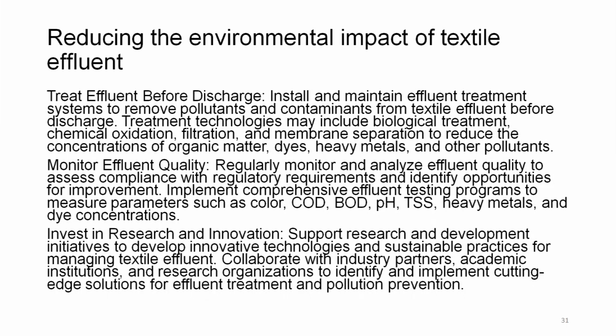Treat effluent before discharge. Install and maintain effluent treatment systems to remove pollutants and contaminants from textile effluent before discharge. Monitor effluent quality. Regular monitoring and analysis of effluent quality is needed to assess compliance with regulatory requirements and to identify opportunities for improvement. Implement a comprehensive effluent testing program to measure parameters like color, COD, BOD, pH, TSS, heavy metals and dye concentration.